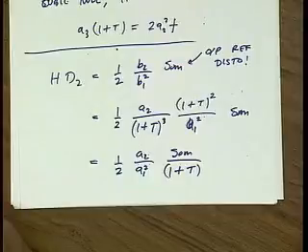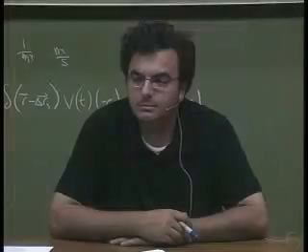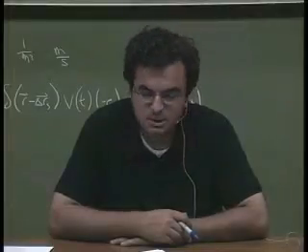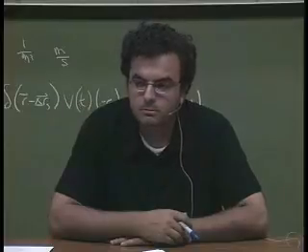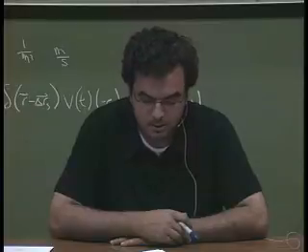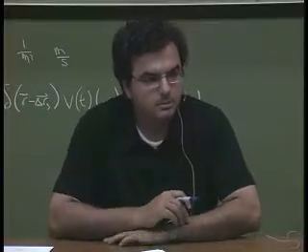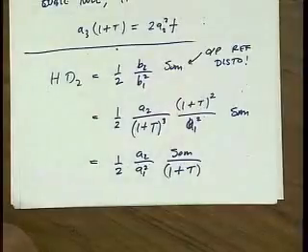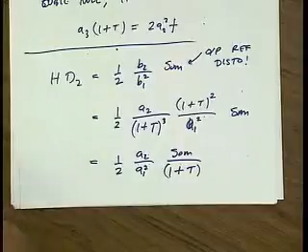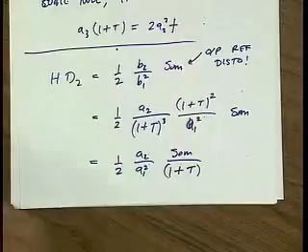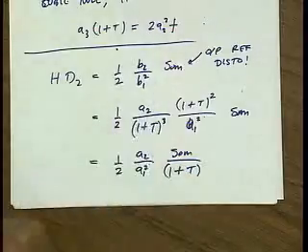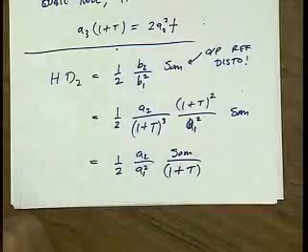When it comes to the end of the day, all we care about is the output of our amplifier. Basically, we know that feedback reduces the gain of the amplifier. So because of the feedback, I'm going to get less signal at the output. So I might as well compare apples to apples. At the end of the day, I need a certain output signal. So that's why I do output referred HD3.